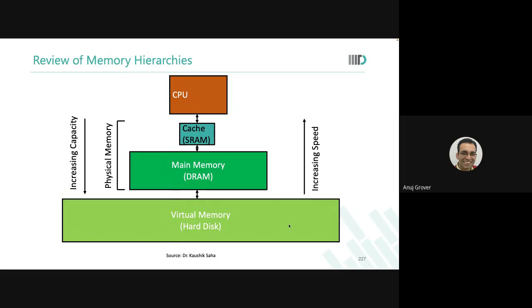But like as we go to smaller technology, the impact of mismatching too much, so we cannot make it very small. Okay, Ria is saying that because there are circuits in the memory which require structural matching and reduced mismatch, as we scale in technology, impact of mismatch is only going to increase. Therefore, you can't really scale performance as much. Okay, what else?